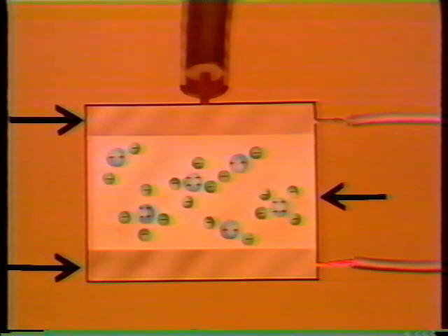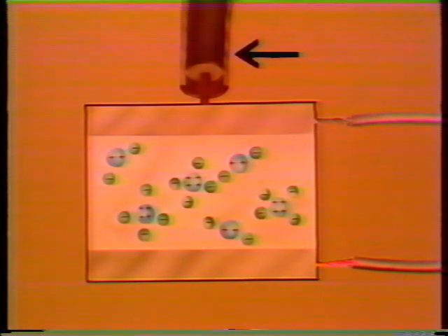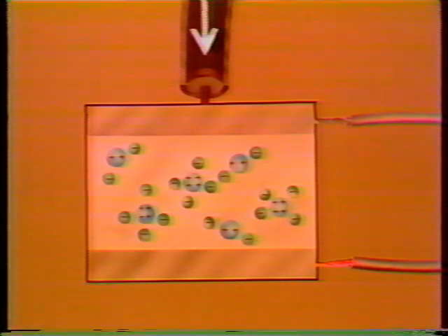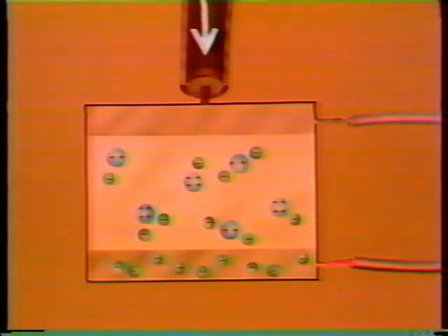It's done this way. There's a crystal between this set of metal plates. A sensing line connects this device to the system in which pressure is being measured. Pressure from the system is applied to the crystal. The force of the pressure passes into the atoms that make up the crystal and drives the electrons out of orbit in the direction of the force.